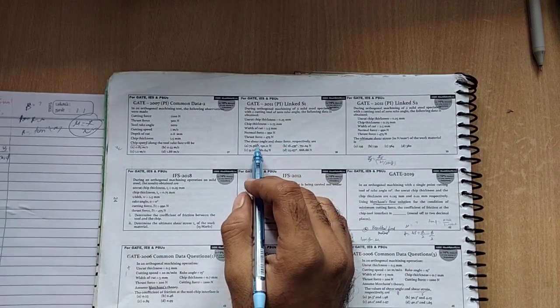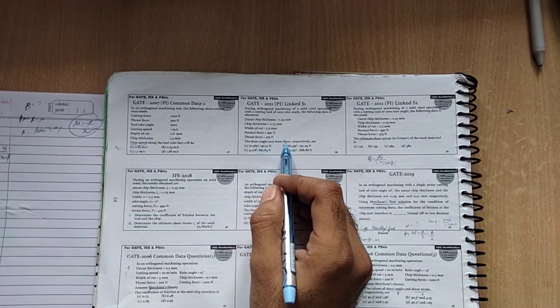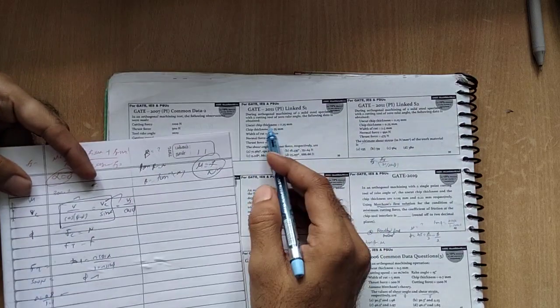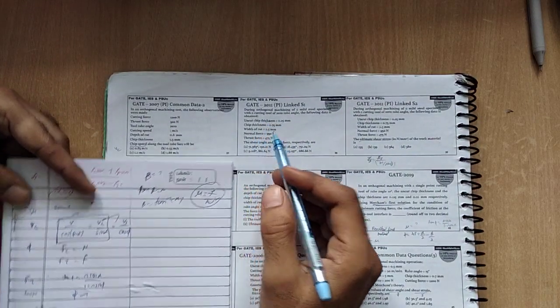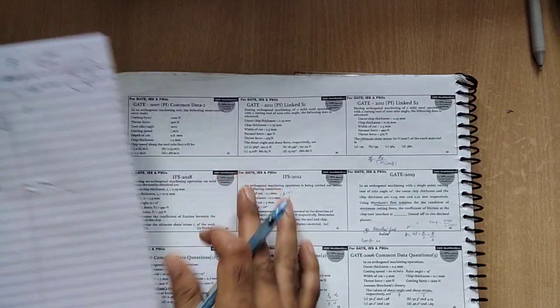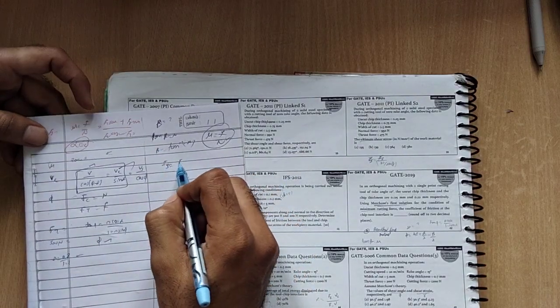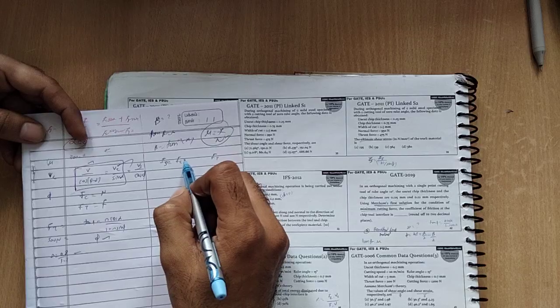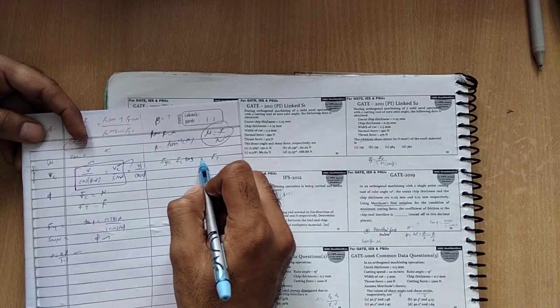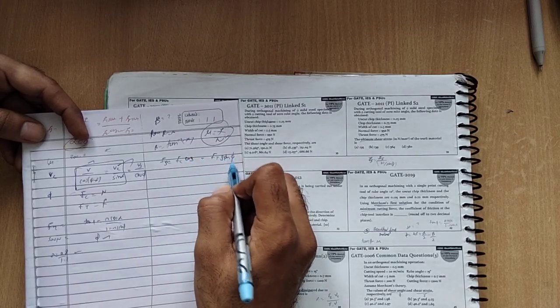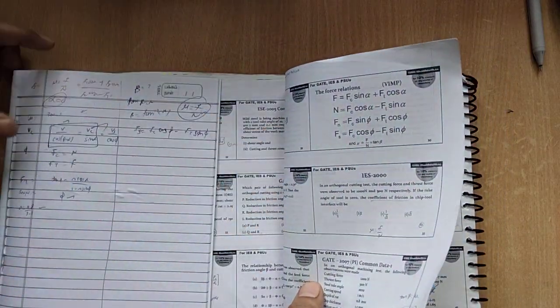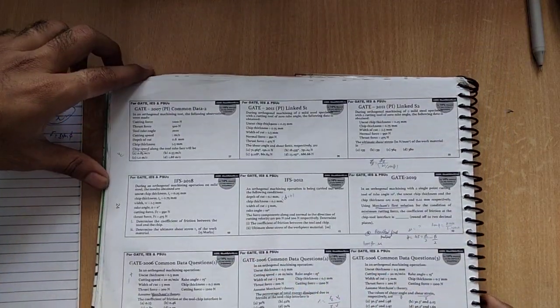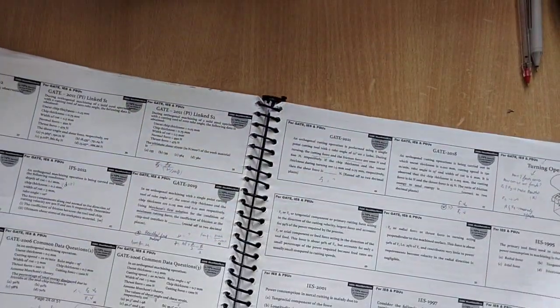Next one, they are asking for the shear angle and shear force. Shear force is a simple thing. Since they have given the normal force, the normal force is the cutting force and the thrust force is this. So F is given by Fc and Ft: this one will be cos, this one minus sine. For the shear angle, we put it here and calculate the shear force. That's it. I think you are able to understand.